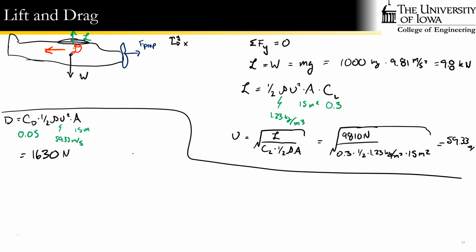Find power, right? The way to calculate power is the force being applied to a moving object times the speed at which that moving object is traversing. And so for the power produced by the prop, to keep it moving at a constant speed, the force of the prop has to counteract the force of the drag.